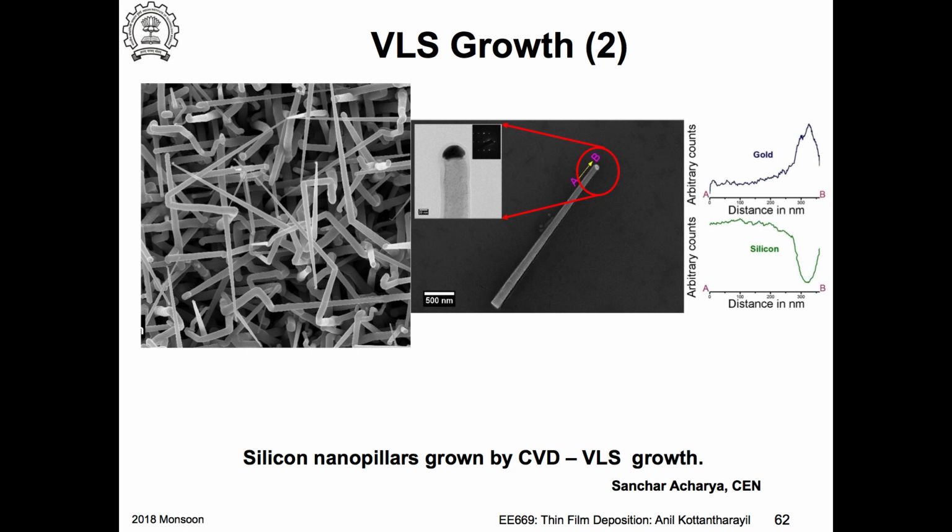Okay. So you can also see them changing directions as they grow. That's attributed to change in the pressure in our reactor. If you can also grow straight arrays of straight nanowires, then you need a very precise control on the pressure. Okay, so we don't have that. So this pressure fluctuates. You can see this.